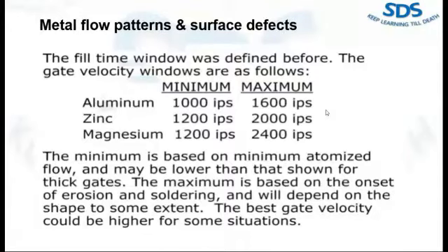So we need some casting pressure, minimum casting pressure. Minimum casting pressure we use is 600 to, you can say, 1000 kg per centimeter square, some range as per casting application. For casting only an aesthetic part, 600 to 700 kg per centimeter square is required. On the other hand, an engineering or leakage proof part requires 800 to 900 kg per centimeter square. So according to that, we need the minimum gate velocity.